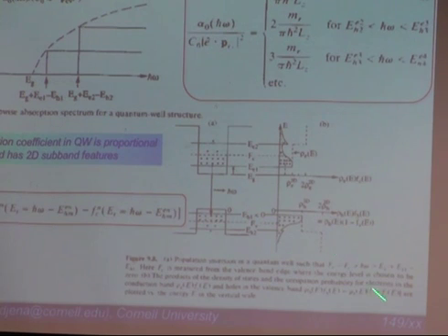And similarly for the valence band. So these are electron and hole densities in the conduction band here, and hole density in the valence band. You see the valence band has many more holes. The reason for that is the valence band effective mass is typically much larger than the conduction band effective mass. You know, heavy holes and all. This mismatch is actually a bad thing for lasers, and people go to great lengths to make sure that it's not much of a mismatch. They are more symmetric, and I'll explain why very briefly. So is that clear though?